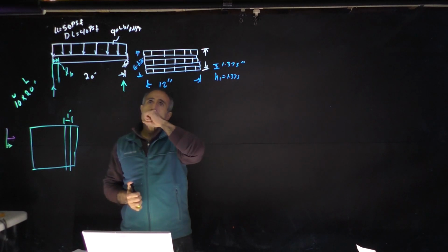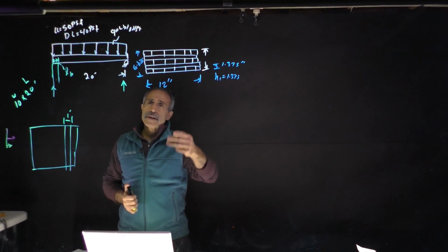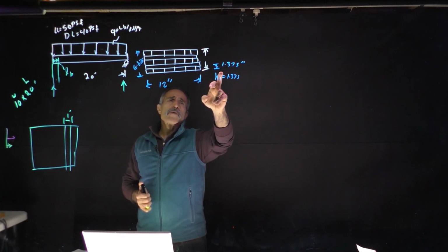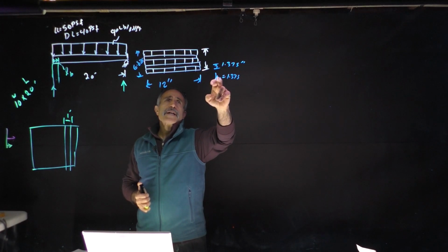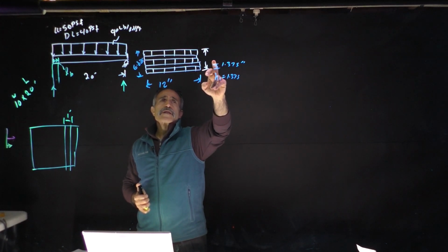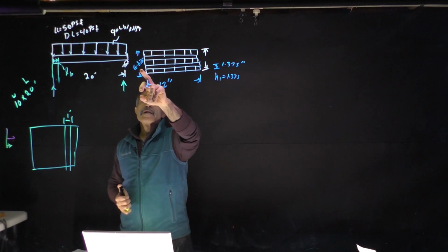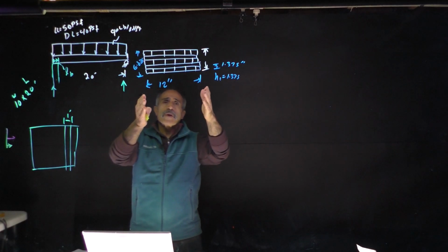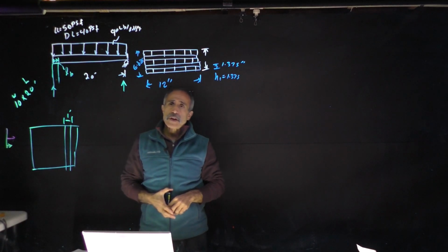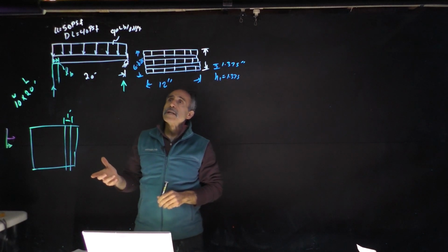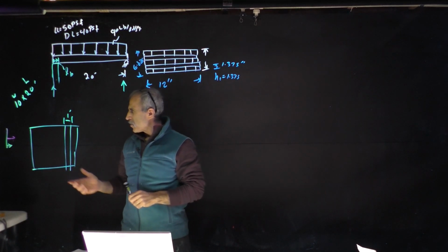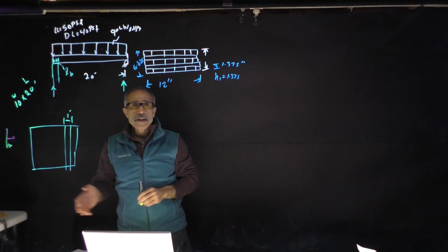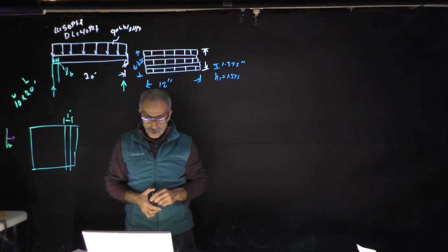The panel we're going to think about could be 3 layer, 5 layer, or 7 layer. We're going to go with the 5 layer, and each layer is about 1 3/8 inches thick. That will be H1. Your total thickness is going to be 5 times that, which comes out to 6.875 inches. The width we cut out is a 12-inch width. We're going to use the CLT handbook, PRG 320, and NDS also. All right, let's get to work.